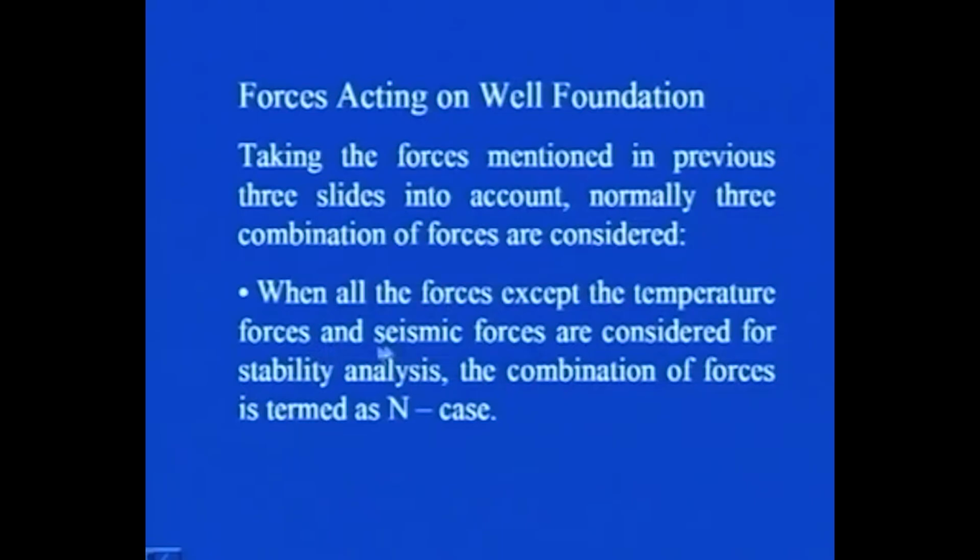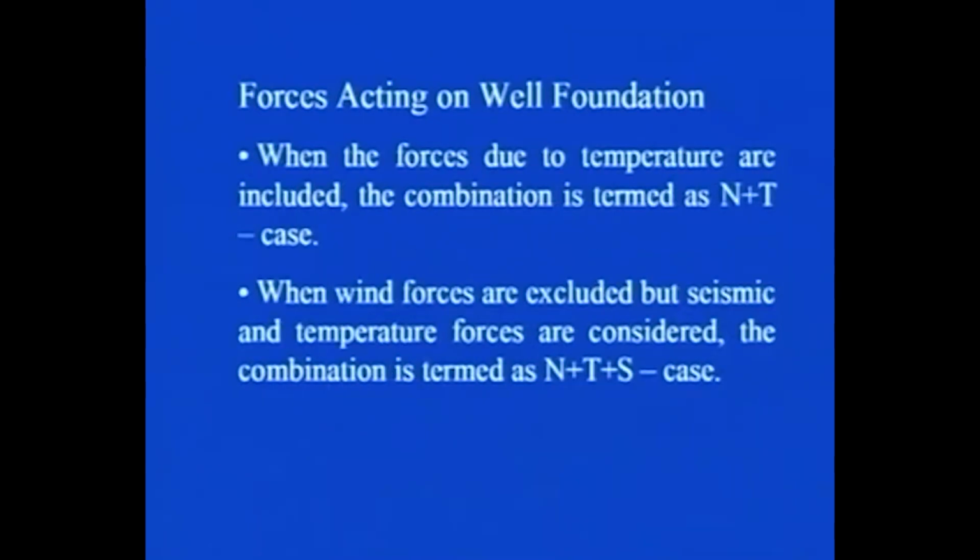When all the forces except the temperature forces and seismic forces are considered for the stability analysis, this combination of forces is termed as N case. So, all those forces which I have already told you, if you ignore temperature force and seismic force and consider all other forces while you analyze the stability of the well foundation, then this particular combination of forces is termed as N case.